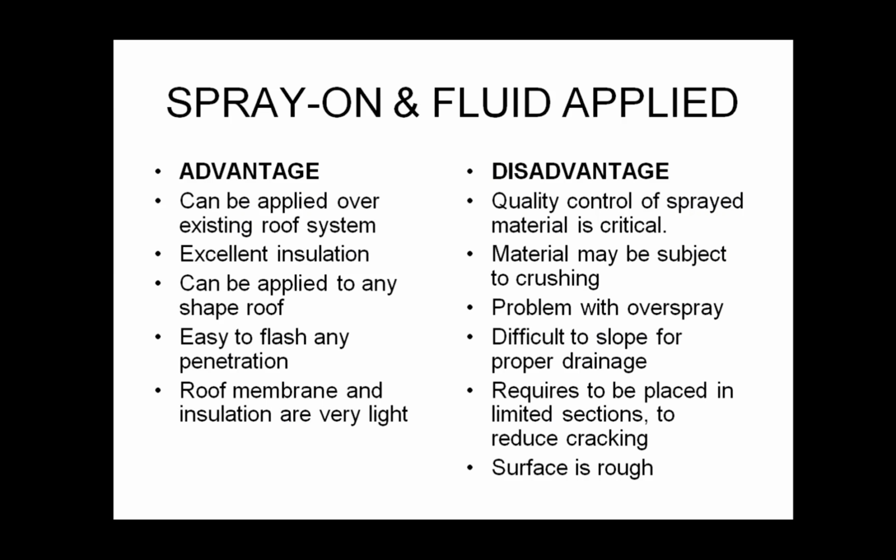And it has to be applied in almost like sections, so that you have time for the material to set and shrink a little bit, most likely, and then you apply your next section, so that it's not one large spray on and then it pulls apart a little bit as the material sets or shrinks. And then lastly, it's usually a rough surface because you're spraying this on. It's almost like a shotcrete or like the insulation and or concrete that you see sprayed around a steel beam for fire protection.